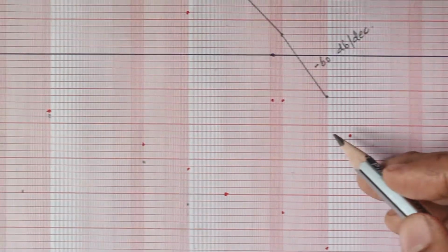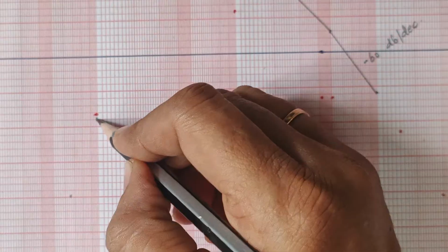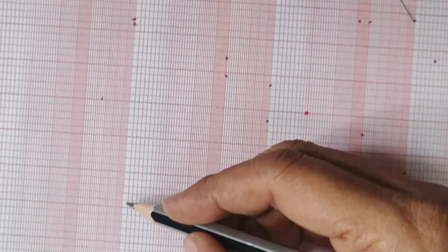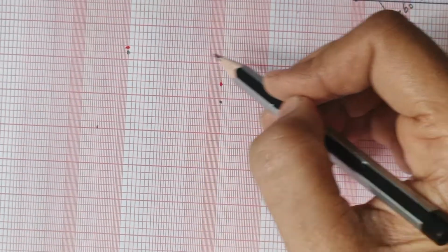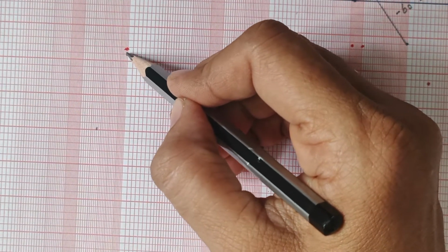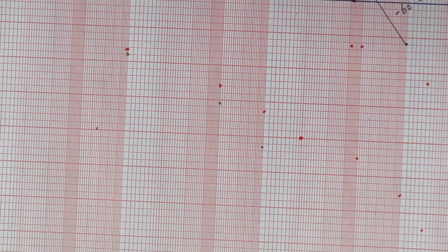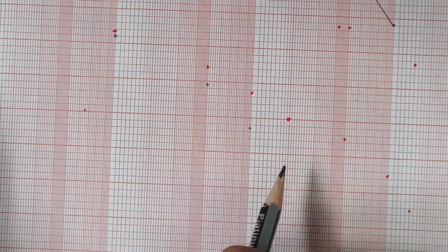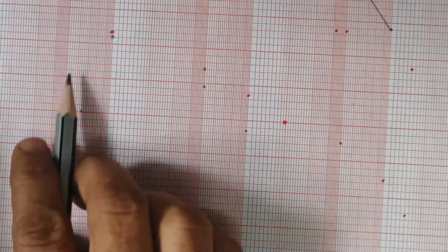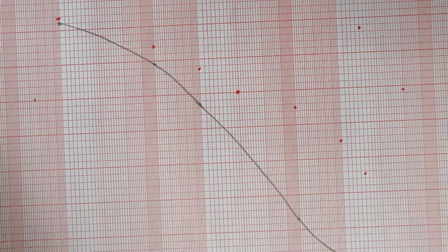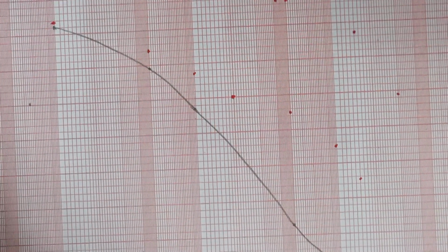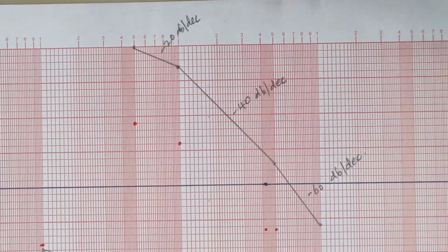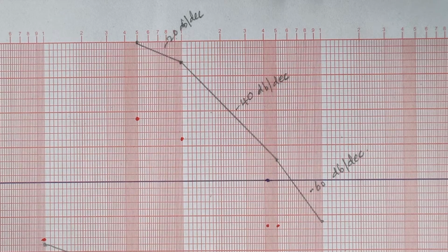So when you move across, you see here is our first point at 0.1, and the respective angle is minus 96. So likewise, you just plot the remaining points. Here I had again used pencil to keep these points. Now I am going to join these dots using freehand. So this is our phase plot of the uncompensated system and this is the respective magnitude plot of the uncompensated system.